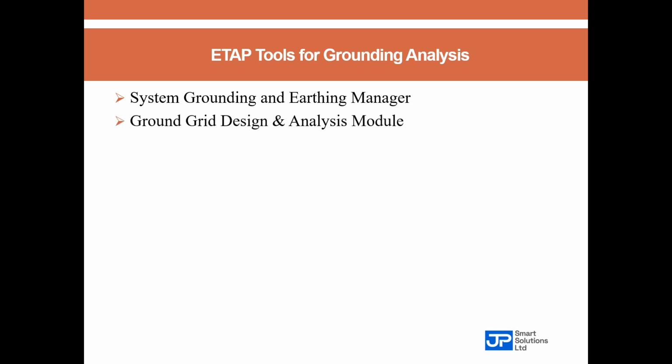Secondly, we have the ground grid design and analysis model. Now, this is extremely useful for substations as it calculates what we call the mesh voltage, the step and touch potential, which we mentioned earlier, and verifies compliance with the IEEE 80 standard or the IEC 60479 standard.